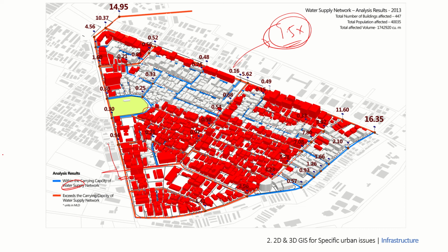So that's why, if you see the master plan, they must have put 40 LPCD, 40 LPCD of water supplied. What is recommended? 135 LPCD is recommended, whereas the master plan says we have achieved 40 LPCD, and in reality we took a primary survey of almost all the buildings, and we were able to calculate that it's around 20 LPCD that people get there. Why this happens is because we don't have infrastructure in place.